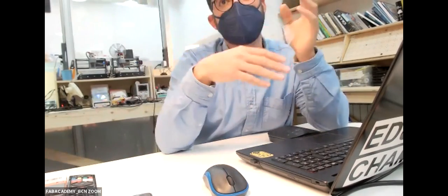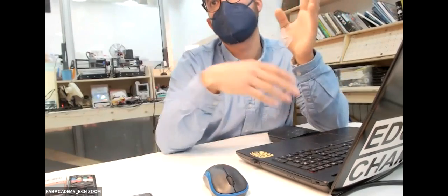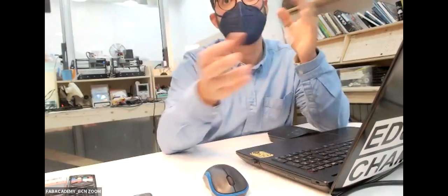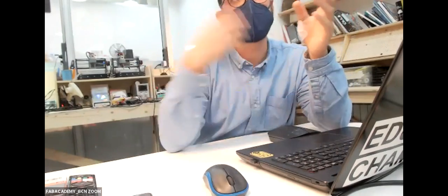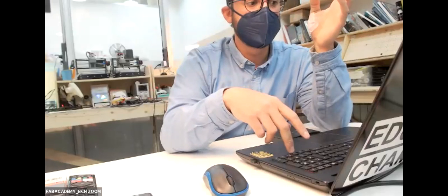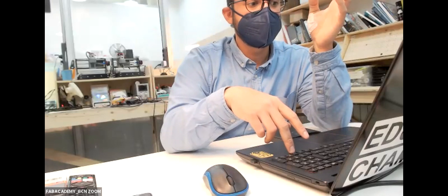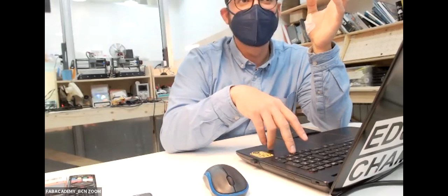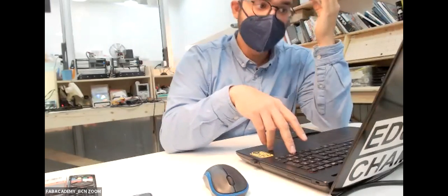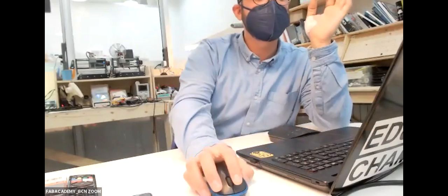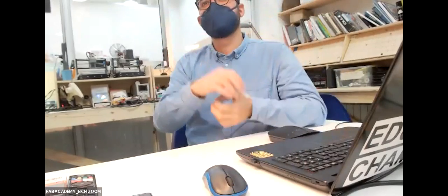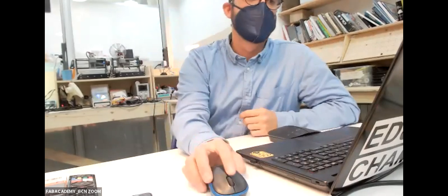But in this case, you cannot cut carbon fiber with a down cutter. You need to use a straight one so it doesn't stay. You need to use low RPM to compensate, so the water doesn't splash everywhere. This is, for example, cutting a little drone frame. There are a lot of things, techniques and little tricks that you can use for milling.